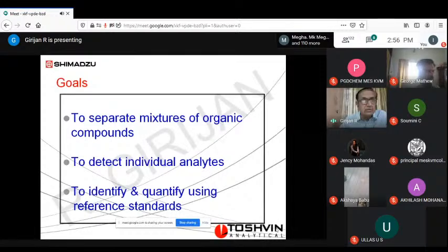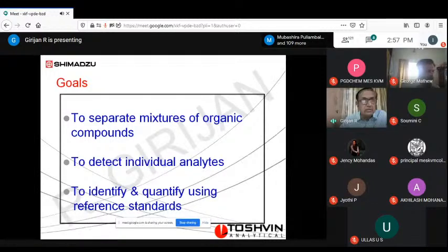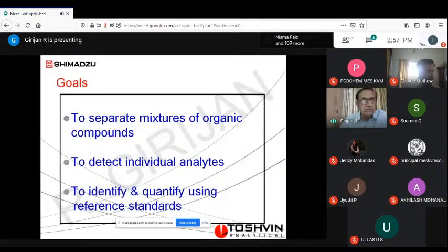It's an example of inorganic analysis. They are inorganic gases. I can think of separating carbon monoxide and carbon dioxide at very, very low concentration. It's an extremely important application in the petrochemical industry and fertilizer industry: carbon monoxide, carbon dioxide separation in some of the gas streams. A very, very critical analysis, and we can use GC for that. It's an inorganic separation, but all these compounds are already in the gaseous form, so for us, it is very easy. So there are very few samples like gas analysis where we can use GC for inorganic separation.